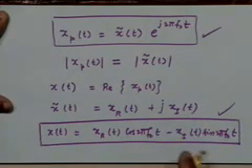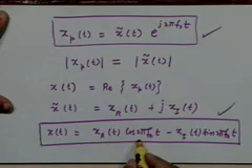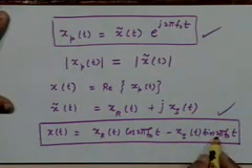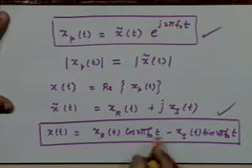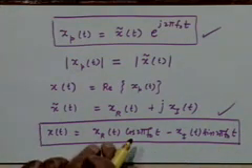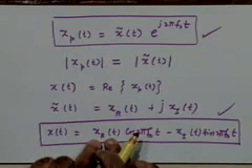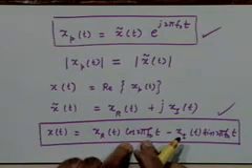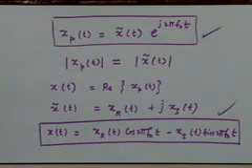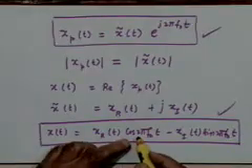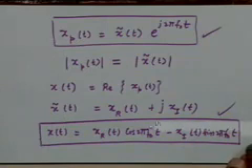The bandpass nature of the signal comes out from the fact that there is a sinusoid present at frequency f naught. What is important is it is a product of a low pass term and a single frequency term, or a band pass term. So the band pass signal can always be thought of as a product of an appropriate low pass signal with a carrier signal. That's what it really boils down to.